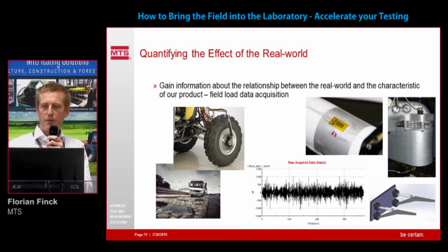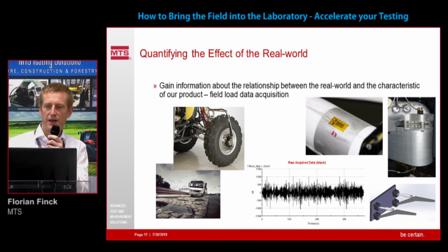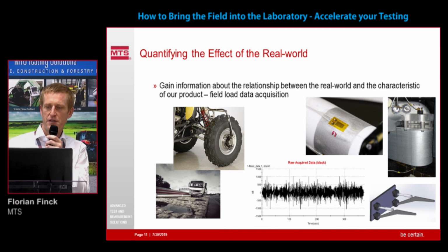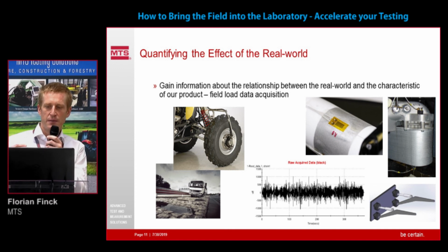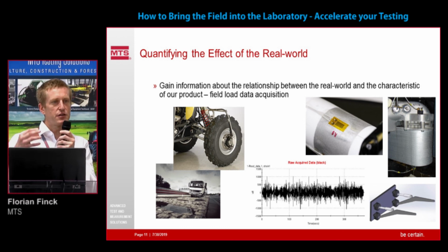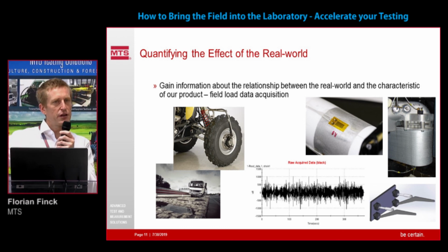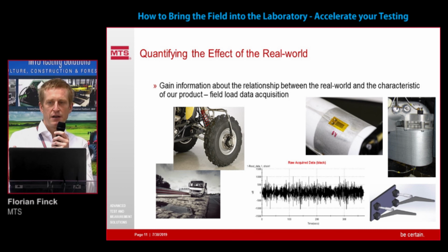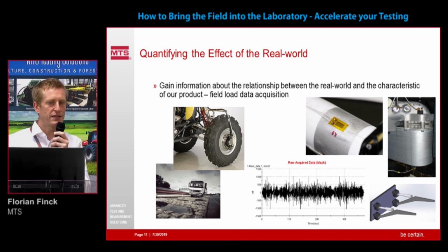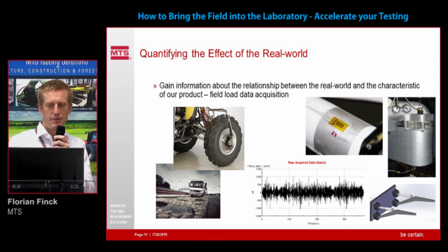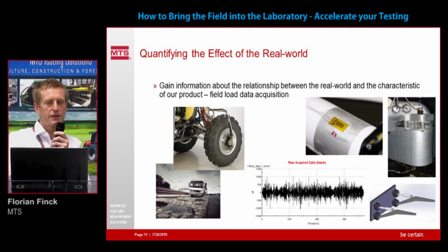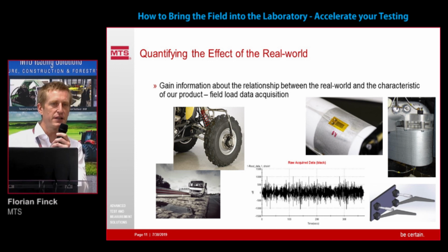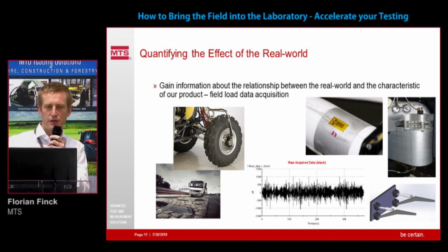You can use accelerometers to evaluate the behavior of your structure, or like in this example down here, you might use an array of force transducers to derive a 6 degree of freedom load history on a shovel of an excavator or lift truck or something like this. So the target of this is to gain information from the field, data that you can use as an input for your test.